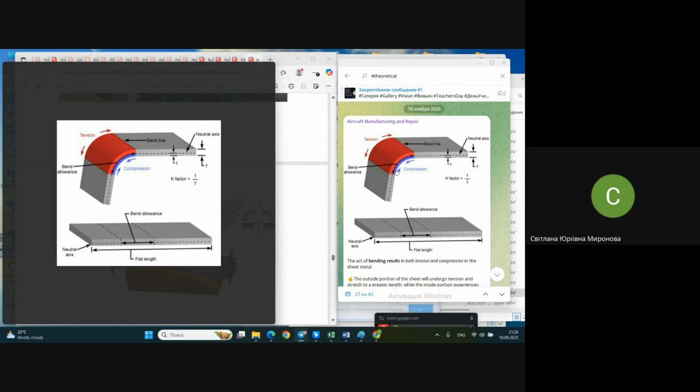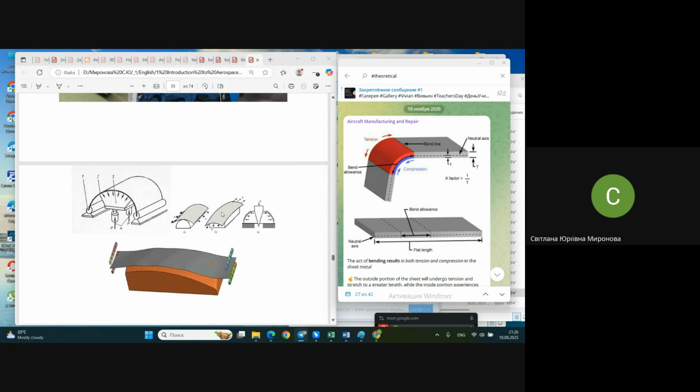Not even much force is necessary, but the table of equipment must be huge. No, we don't like it. We'd like to save money. How to do it? Stretch forming should help. Stretch forming will use only a punch and clamps on the sides.